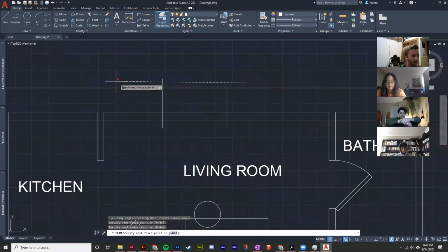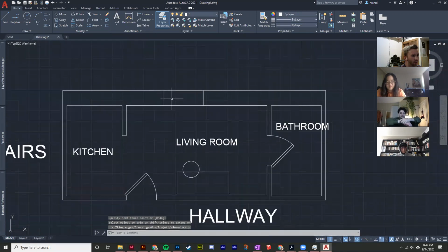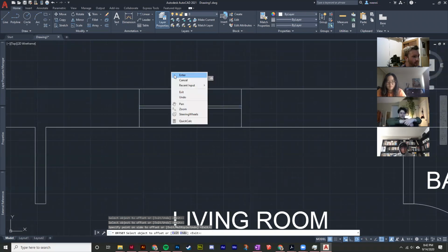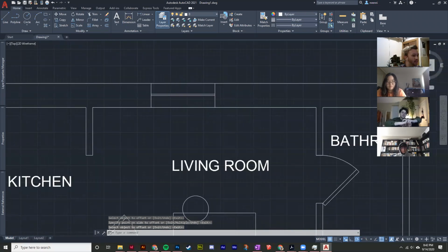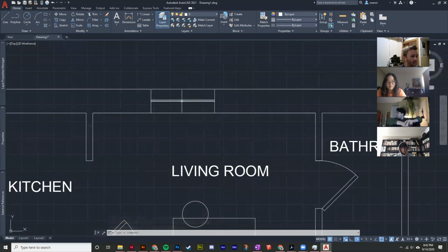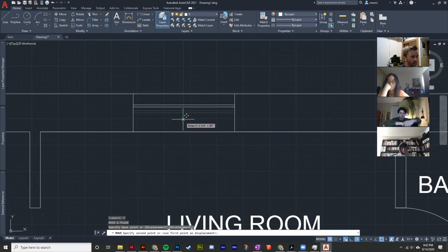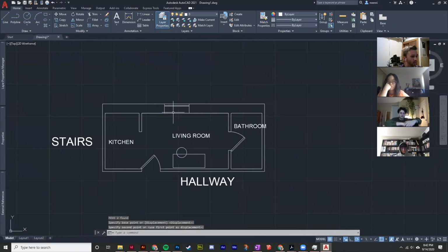I'll trim it up, so get rid of these lines. And then usually you draw the window pane as well, like the layer of glass. So there's the window, and you can do that also as a thickness, just like a wall. Let's do 1 inch. It's usually pretty thin. It's also not in the center. So you can see here, I've drawn it in the middle of this exterior wall, but it actually sits a little bit more towards the exterior. So I just selected these two by using my green selection. If I wanted to use blue, I would select the whole thing, and then M, enter for move, and then select my base point, and then I can scooch it a little bit higher to the top.